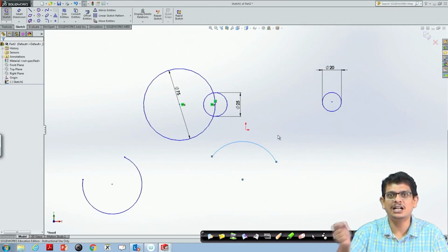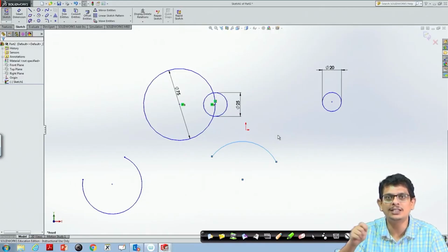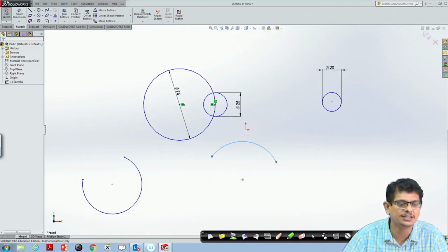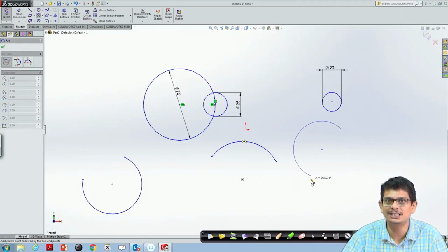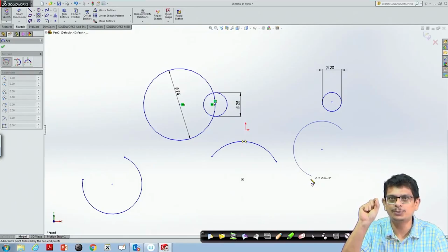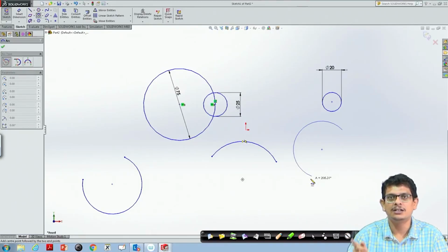So, the direction along which you are moving, try to construct that. Now, let us go in the clockwise direction for the same arc. Center point arc, first point arc. Now, I want to move in the clockwise direction. If I am going to do clockwise direction, your GUI always says that you pick the first point, but you want to end the point in the clockwise direction.